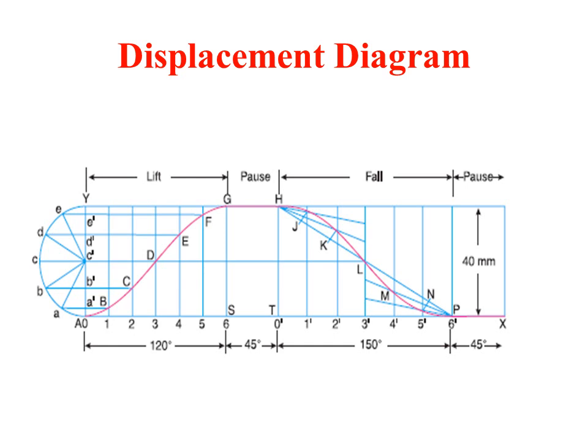Now from P, when you draw the line, it intersects 5 dash at N, again it intersects the next line 4 dash at M, and again it intersects 3 dash at L. So join all these points with a smooth curve. Next, you take H as the center and again join lines to the midpoints where it is divided. Now when you draw from H, it intersects 1 dash at J.